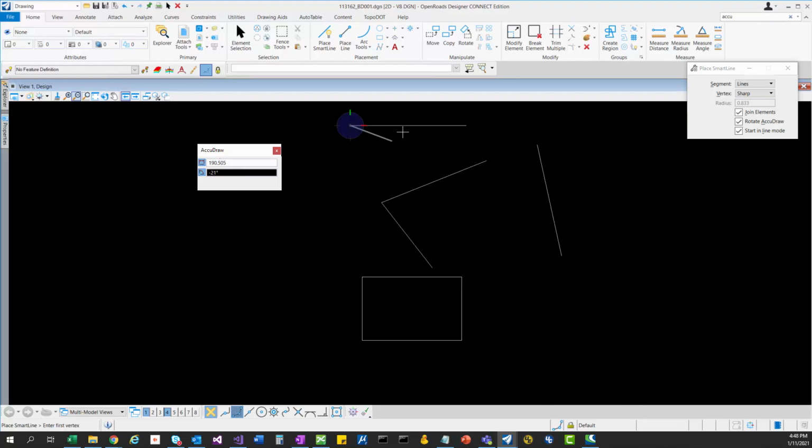So I haven't even drawn anything. I'm just showing all these different capabilities that we have, right? If you hit the X key to lock X value, it will switch your mode back to polar or rectangular mode. Same thing if you hit D or A, it'll switch you back to that mode there. Okay. You can hit the tab key to toggle between your X and Y values here. So I'm hitting tab and you see how that's toggling back and forth.